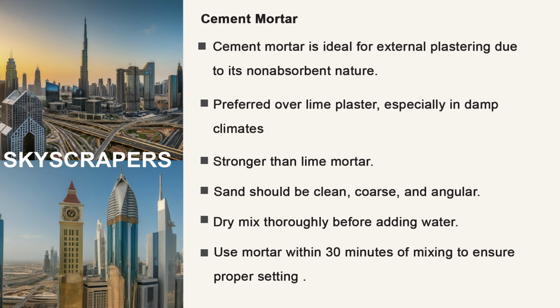The important thing that we have to consider is, for the best result, the sand we use here should be clean, coarse and angular. The mortar should also be dry mixed before water is added and must be used within 30 minutes to ensure it sets correctly. That is pretty fast, right?